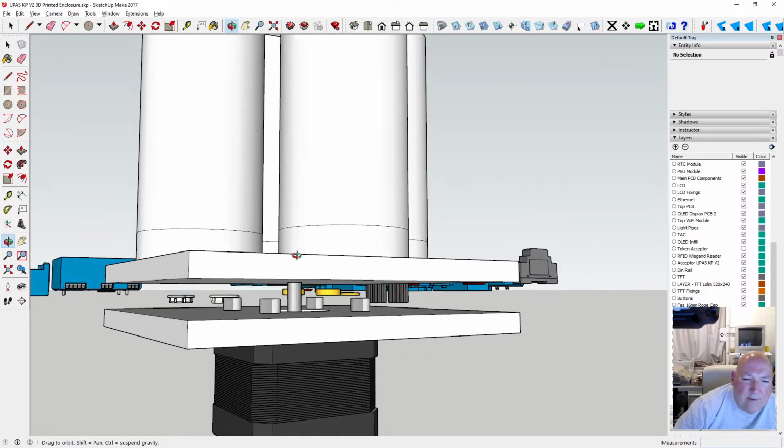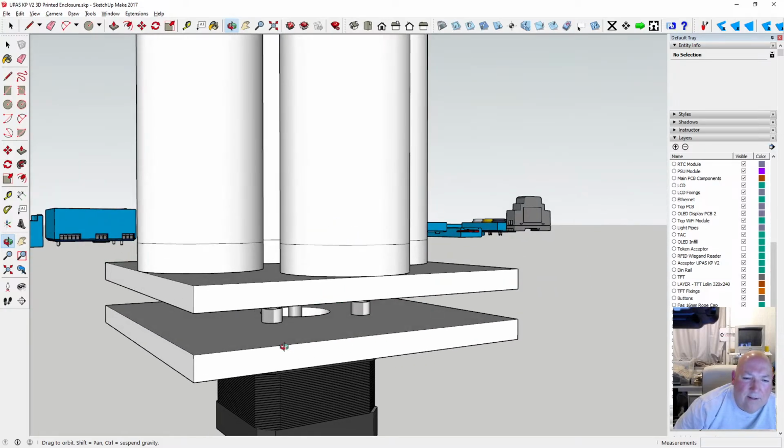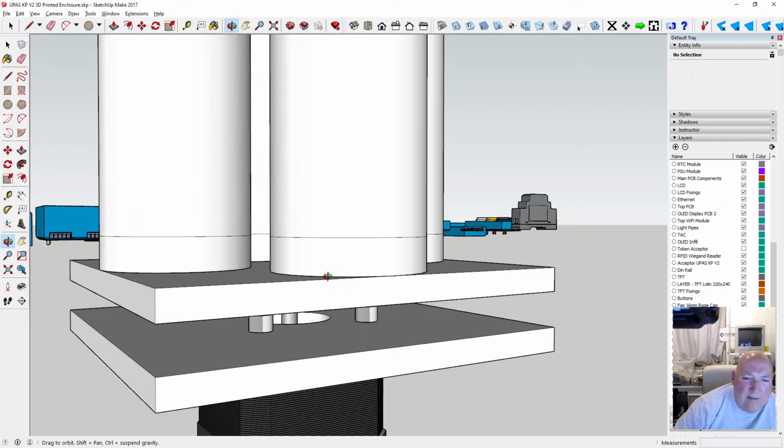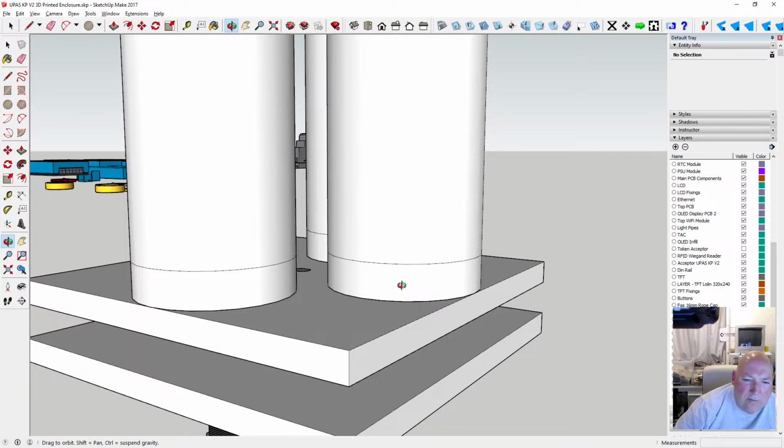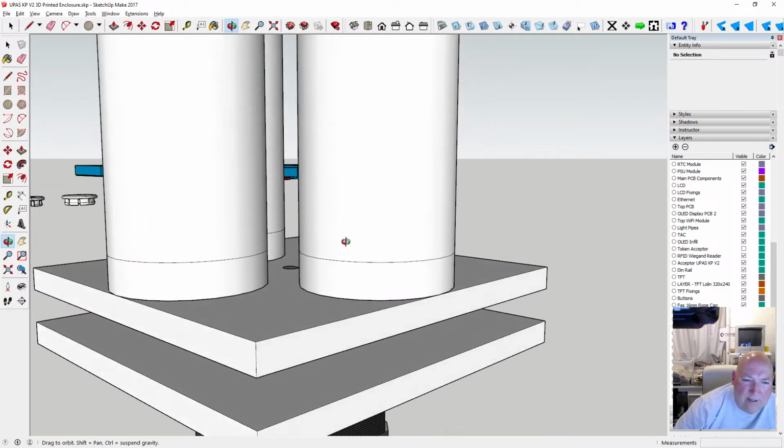So we're going to need a static pin mounted here that comes up through. And if we have a groove all the way around, the thing isn't joined; it splits. But then this coin tube could have a slot in it to pass the pin round. Then the tube would have to hold the two sides together.